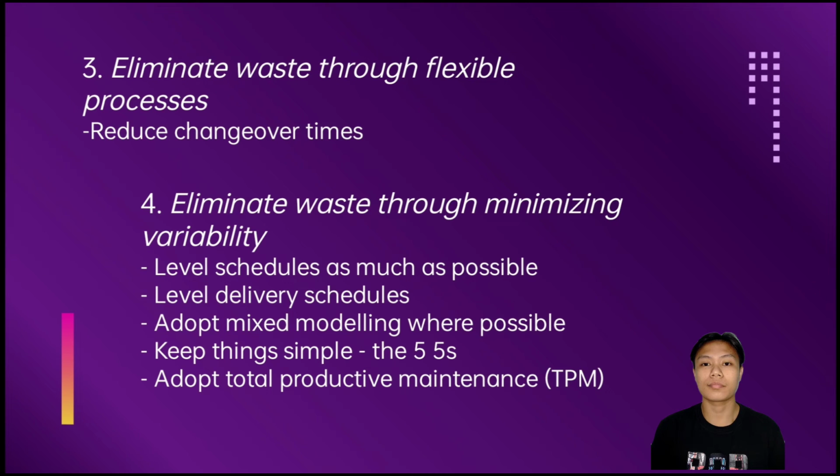Next is eliminate waste through flexible processes. Flexible processes is a concept used in management which refers to how an operation responds to external factors. It includes reduced changeover times, which means reducing the time taken to change over the process from one activity to the next. In fact, flexible processes can significantly enhance smooth and synchronized flow without incurring high costs or long delays. One of the major methods to achieve changeover time reduction is to convert internal to external activities.